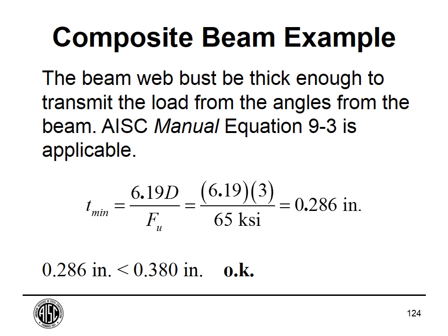And the last thing we'll check on this is the fracture strength of the web at the welds. We still have to check that. Remember, we have 2 welds, one on each side of the web, attaching the angles to the web.